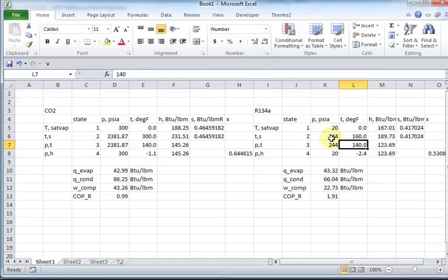Okay. Looks more reasonable for the pressure. Didn't I say the pressure was around 250, 260? Okay, here, 175. You want to split the difference or something? But this is good enough. And so using refrigerant 134a, our coefficient of performance, first of all, our pressures are much different, aren't they? Much more reasonable.